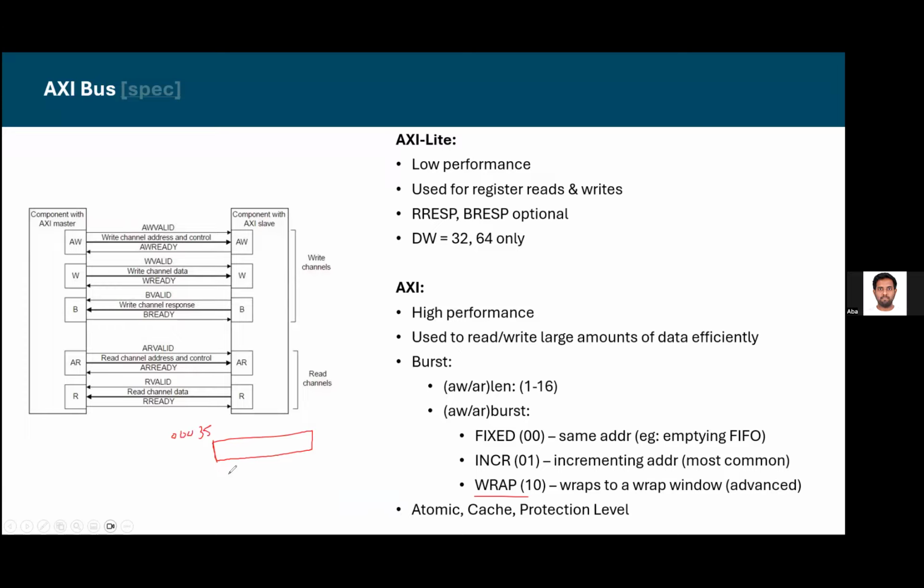It always starts at power-of-two numbers, in fixed portions. So you can set the size and length in such a way that size into length is your cache line. That way you are asking for the entire cache line at once.